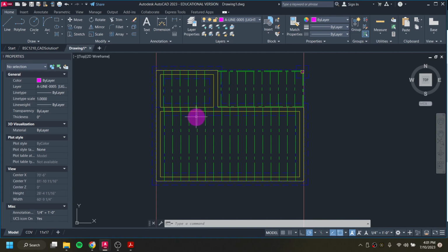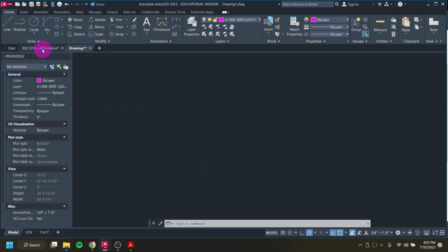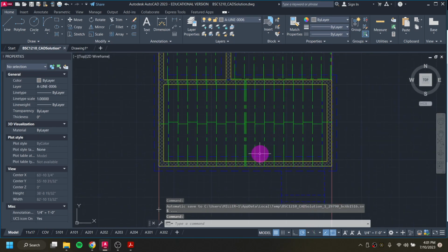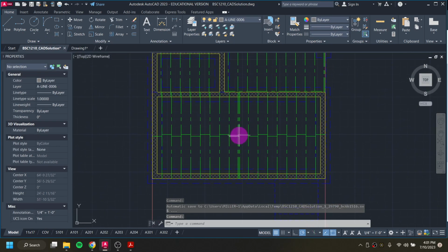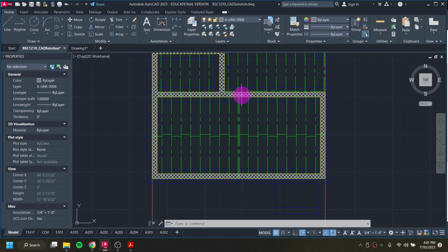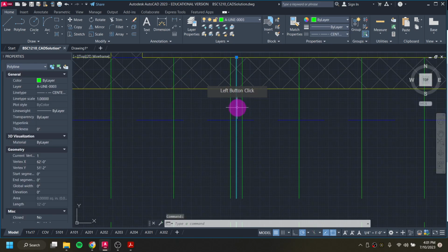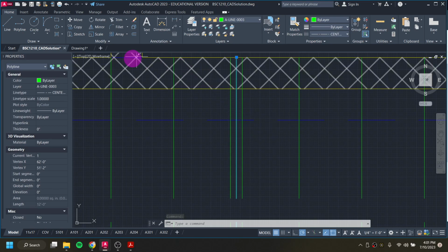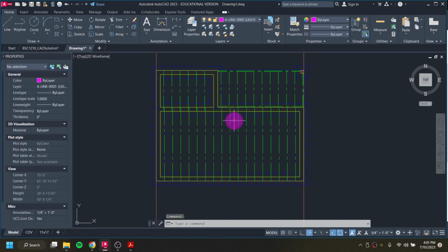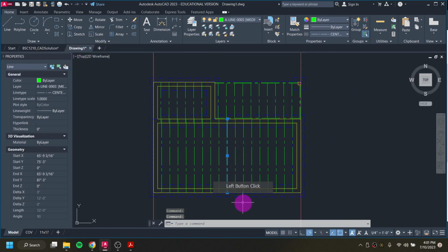So last thing would be our hatch in our plan. Or actually, oops, we still got to do a girder, not our last thing. So we'll add our girder in. So this is 3 2x8s just stacked on each other. So we already have this one in the middle. We just need to go 1.5 inches in either direction here. So this is our middle one.